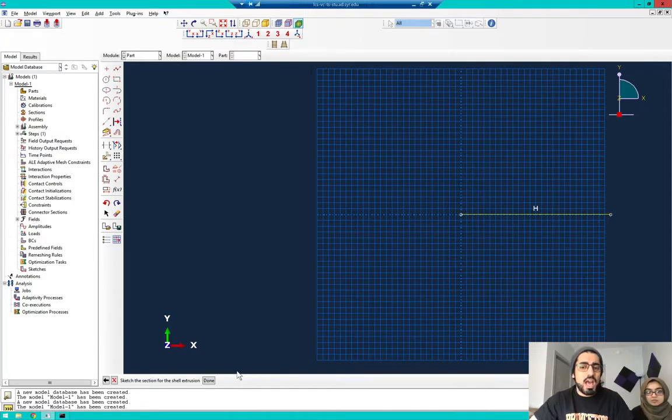Now, you tell me, how did I input them without actually specifying units? I didn't specify units, you saw that. I just put 26. So this is the interesting and sometimes annoying thing about Abaqus. Abaqus doesn't have units inside of it, so you need to make sure that all of your units are consistent with each other.